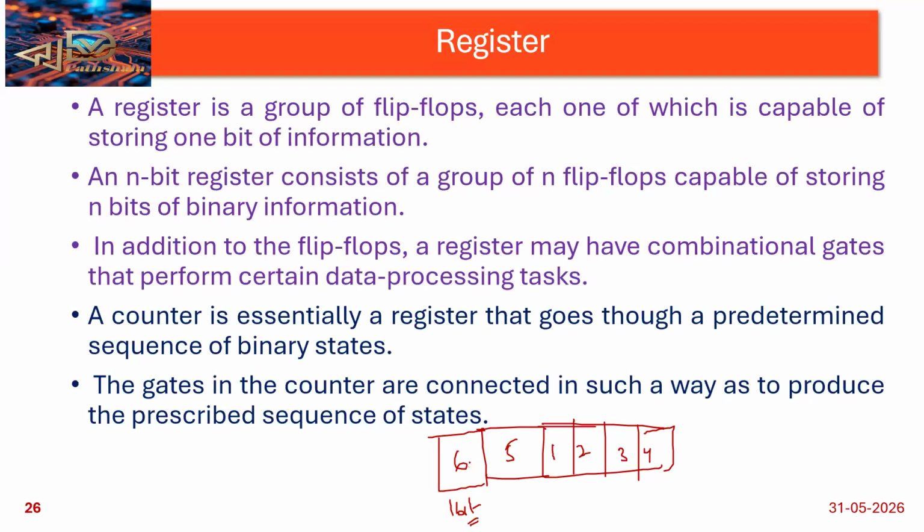Here one more question: these flip flops, which are storing one bit only, those could be anything, right? Like D, SR, JK, T flip flop, anyone. Every time it will store one value only. And one more thing, they are not connected to each other, right? Like there is no carry, not like a ripple thing. They are individual, right?